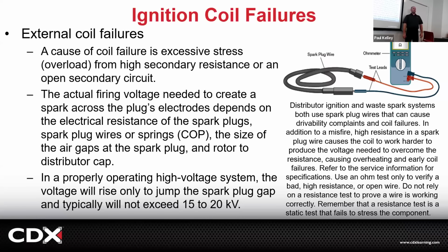Make sense? So if it's a coil on plug and we replace the coil because the coil was bad, yeah, I agree. You need to at least inspect that spark plug. If that spark plug has a big air gap, that's putting more strain on the coil. Makes sense, especially to get premature failures. Premature coil failure would be caused by high resistance.